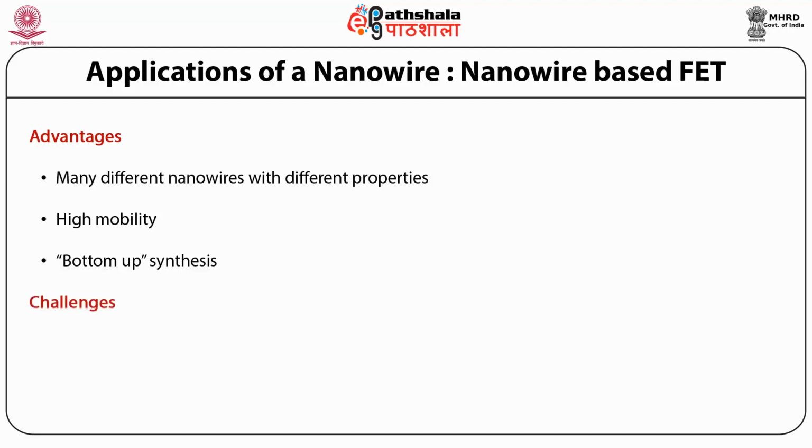Nanowire FET has the following challenges too. The first one is that the integration of nanowire into circuit is a little bit crucial. Controlled growth of having uniform diameter and length is also very tough, and controlling dopant atom is also not easy.